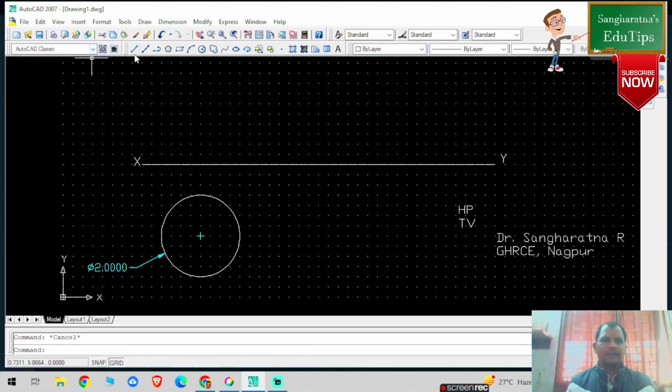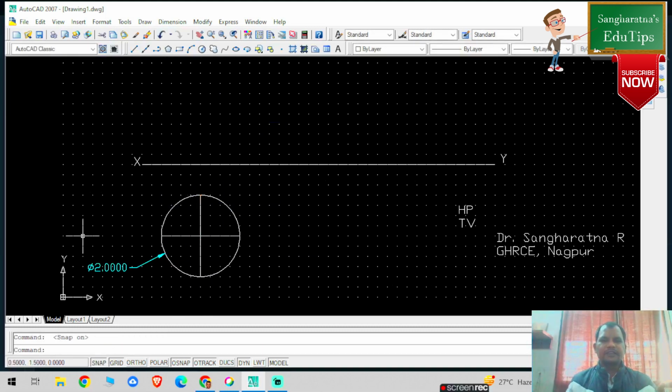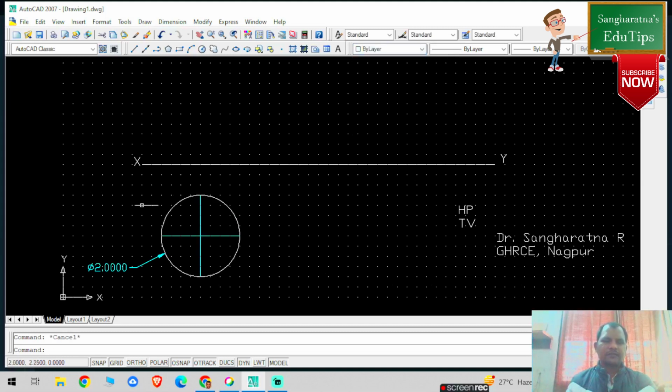I am going to divide this particular circle into equal number of parts, right? And I'm going to convert this into cyan color. So this line and this line I'm going to convert into cyan color. So now I can give the naming, the text. Select any point on the screen. Now I am specifying point 1 and rotation angle is 0.